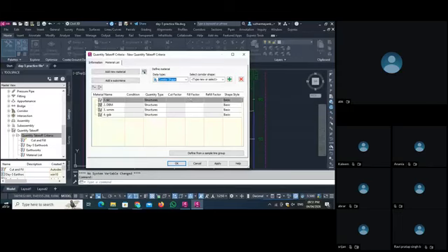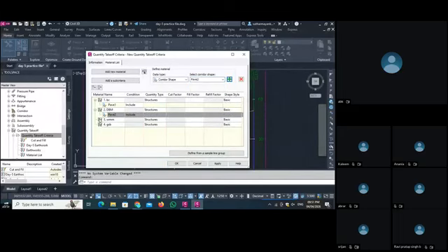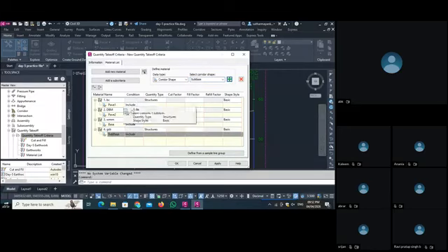So what I say, select the first here, set the data type as corridor shape, and set the pave 1, the first shape here. Then I go to the second type, set the data type the same, and pave 2 here, done. Then for the third, I set base layer here. Then for the fourth, I go for the sub base here. Okay, so I have 4 layers and I include those 4 corridor shapes here.